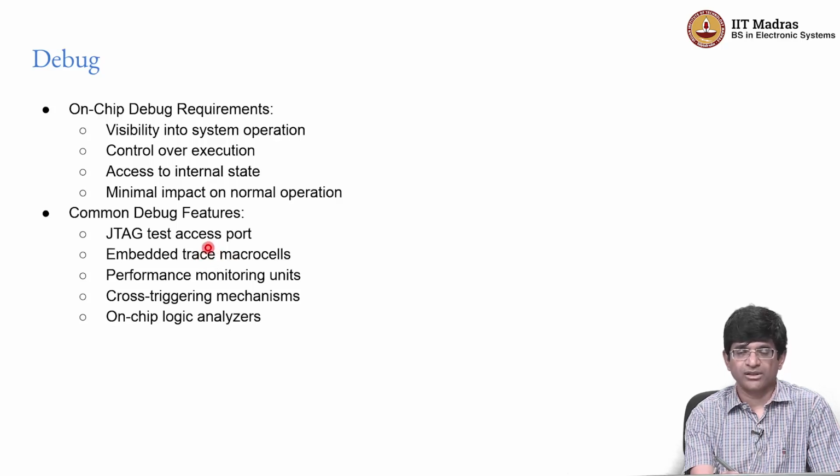You can set those registers to known values, trigger the evaluation of the entire system, read out what the outputs of each of the combinational blocks came out to be, because they get stored into the registers, and compare it against expected values. So it gives you a very fine grained level of control, and of course it is also time consuming, so ideally you should not need to rely on it, but it is a very powerful means of debugging.